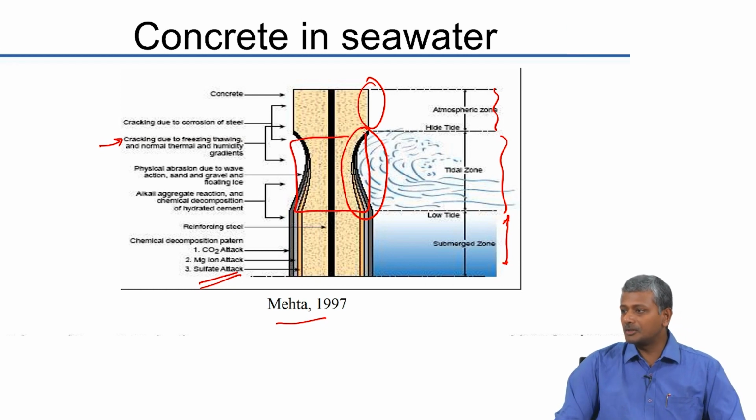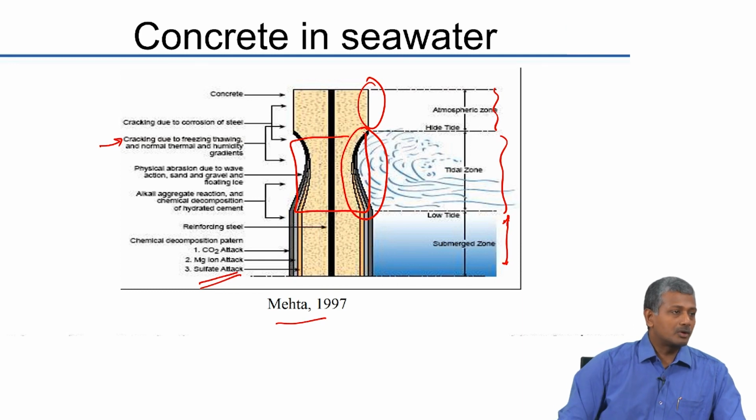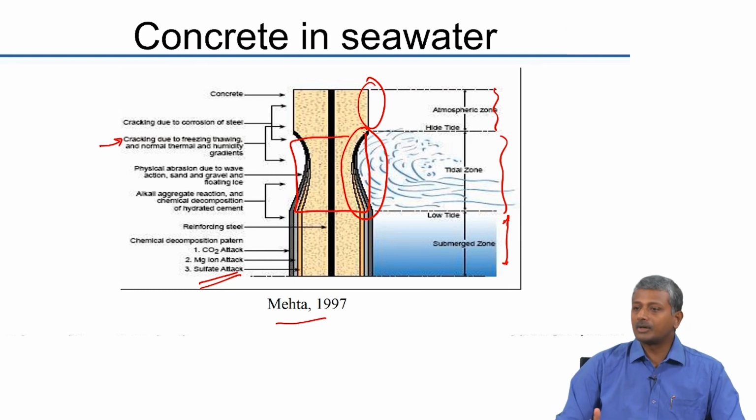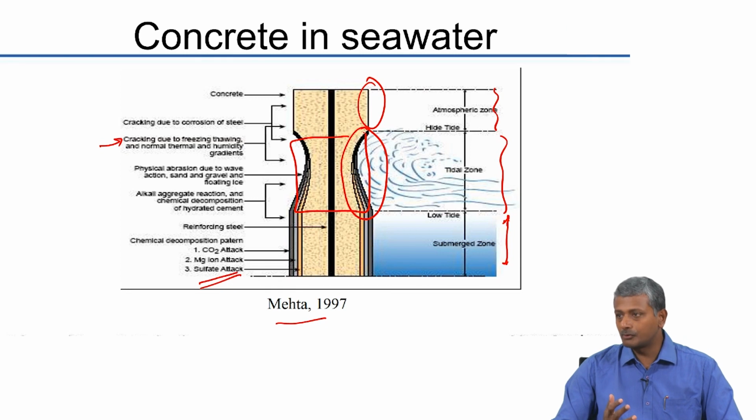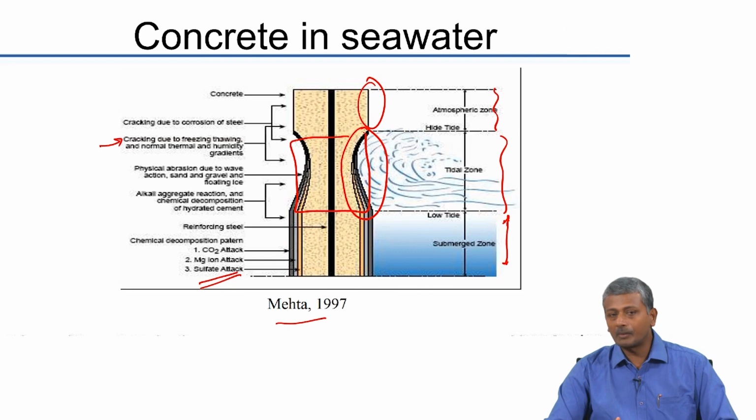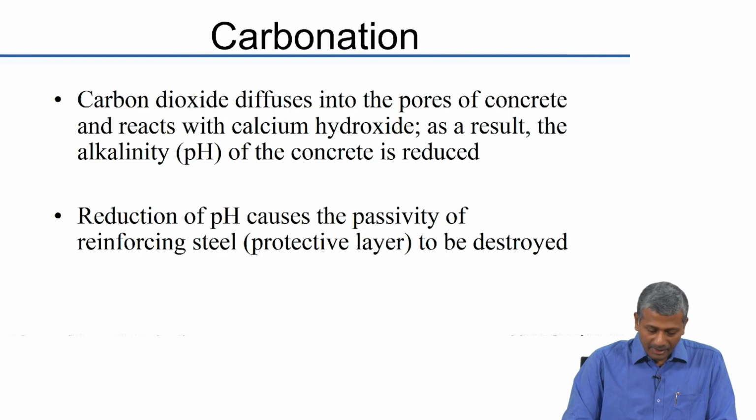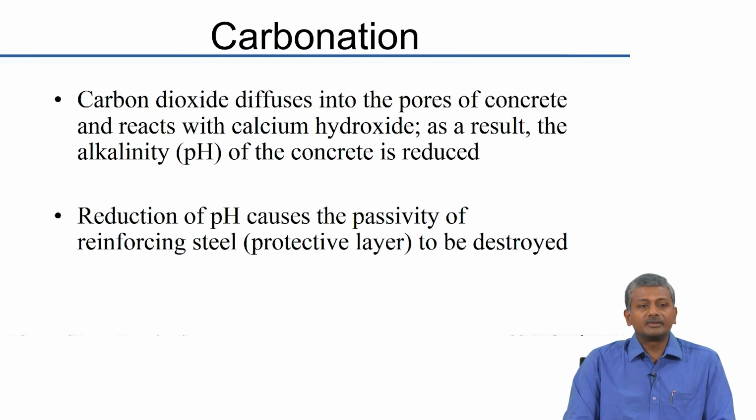You consider that to be the most critical component and design your concrete structure as per that. So, all your requirements for concrete cover over the reinforcing steel, the qualities of the cover concrete, everything has to be based on the requirement of concrete for the splash zone. Now, the next problem that is dealt with in a very large extent as far as concrete structures are concerned